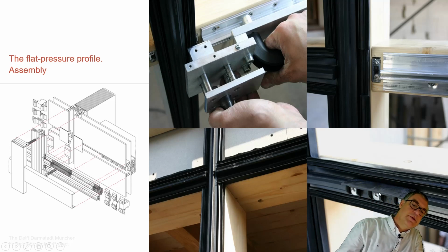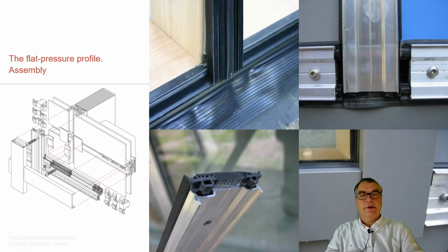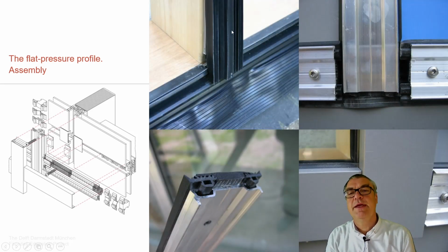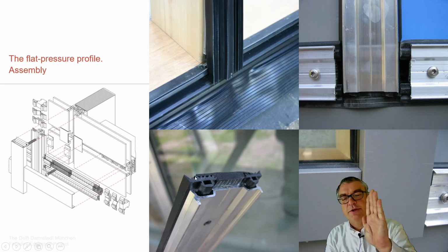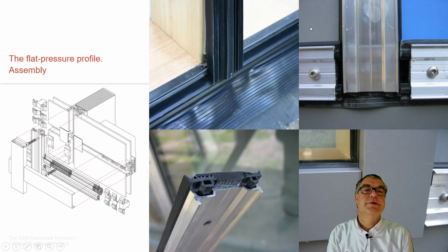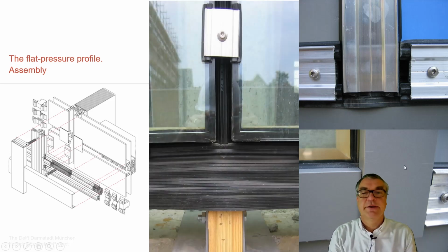This part takes the glass, so it's the bracket which takes the dead loads of the glass, which is also fixed to this aluminium bar as a system. Next level of this, we see the inner sealant system bottom part. We come to that later. We see the outer pressure bar, which is putting the glass in position under pressure, and then which happens here in this situation where we see the vertical and the horizontals screwed through the system into the screw channel, and then the cover cap which is brought on top of it as a total system.